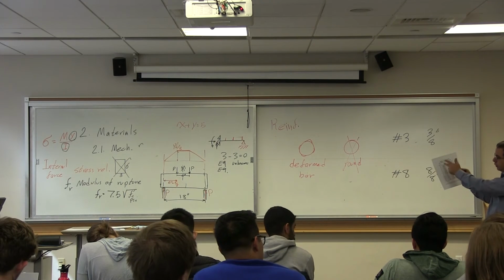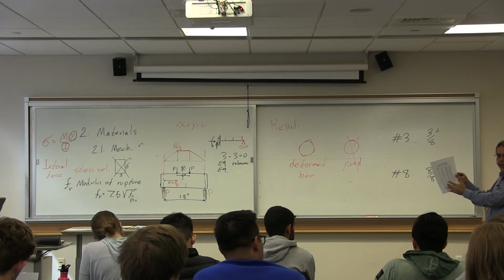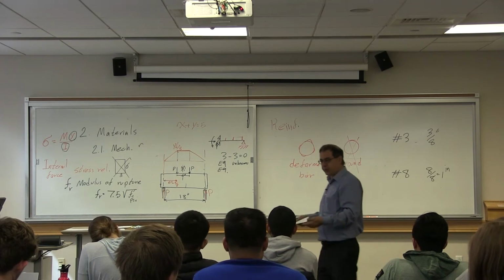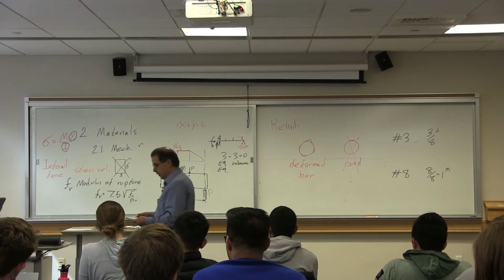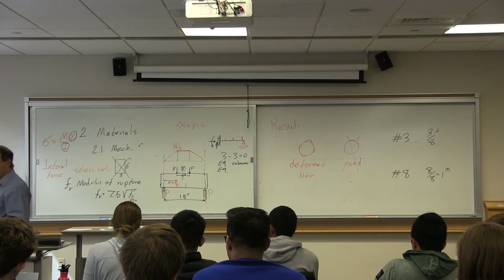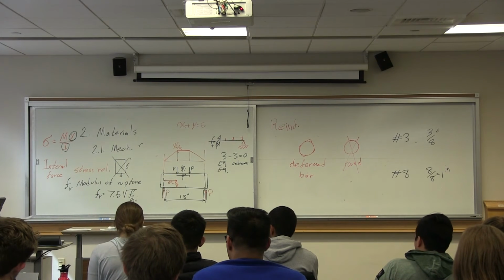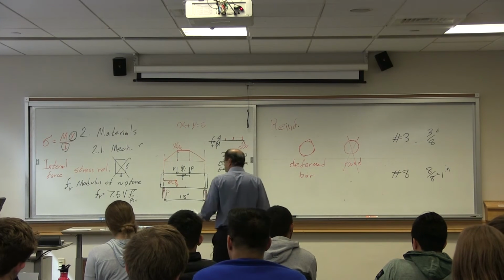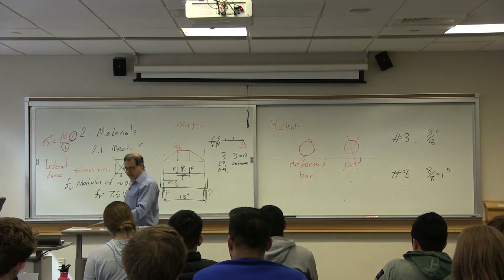But at the beginning of the course, the only thing you need is the areas. After you solve some problems, you kind of memorize it. Number 8 is 0.79, number 6 is 0.44, and so on. So this is the table that gives us the area of the bars.